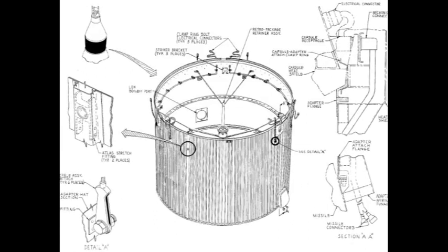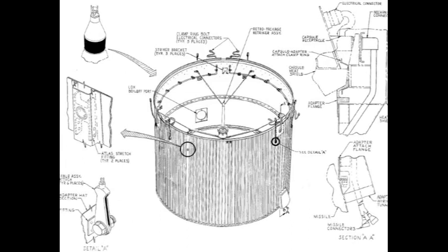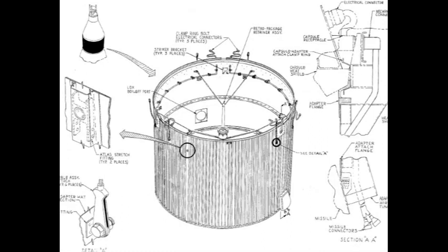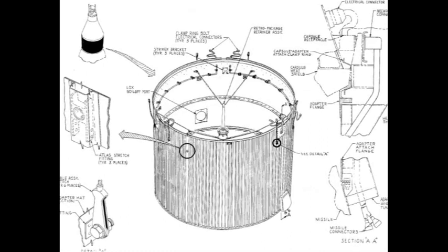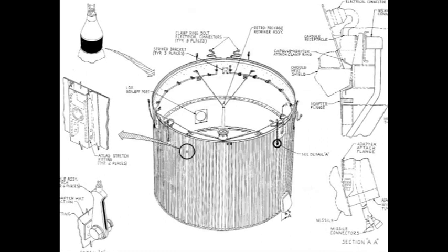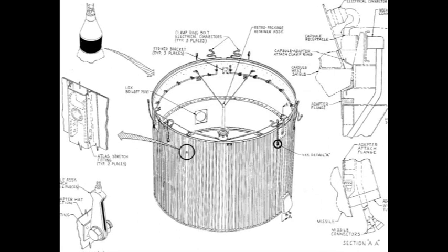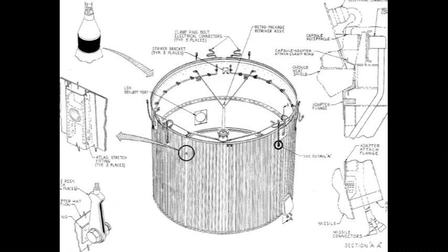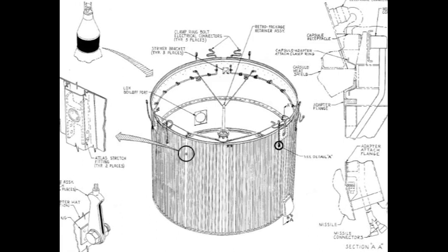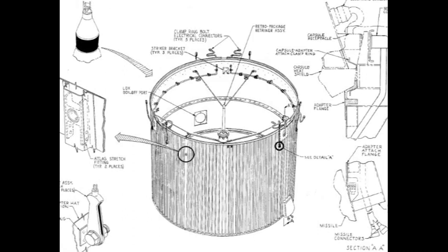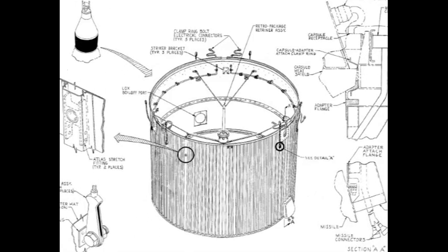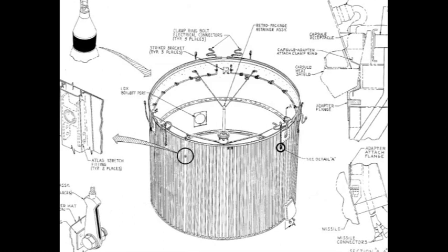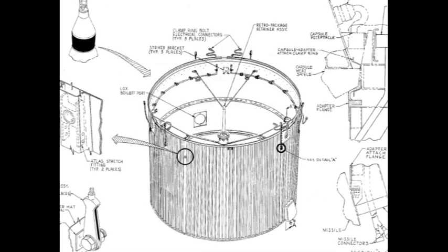Upon adapter and capsule installation to the missile, the adapter is bolted to the missile and the capsule is attached to the adapter. The adapter is of semi-monocoque construction and is approximately 4 feet in height. The adapter basically consists of an outer corrugated titanium skin assembly, riveted and seam welded, to an inner titanium skin assembly, and internally reinforced with 2 titanium support rings riveted between the ends of the adapter.